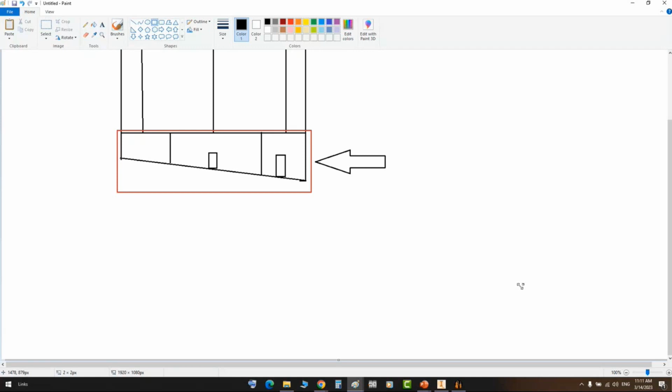But if you would like to add a child to another child, like a nozzle to connect it to another nozzle, or a nozzle connected to a skirt, or an opening connected to a skirt, in that case you have a child and you need to make it a parent. In that case, you will need to make a shift by using an imaginary part. Okay, got it, Mr. Ahmed. Thank you.